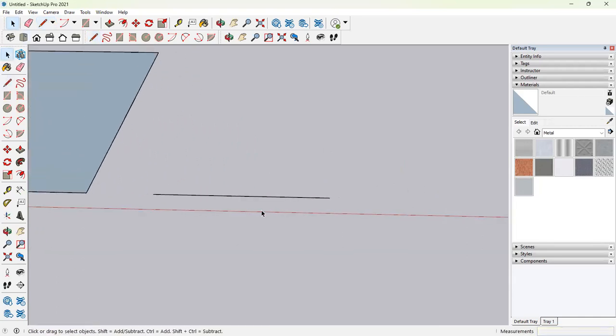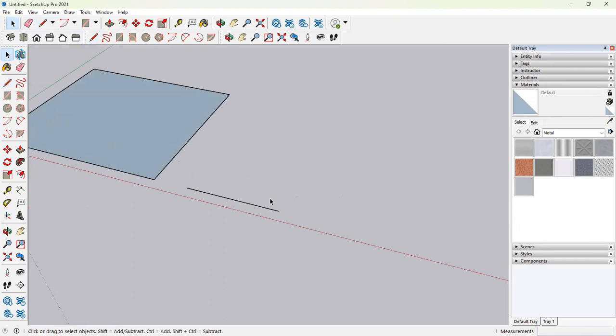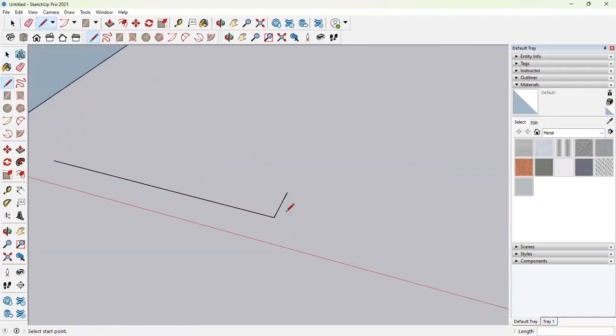This is very important. Dimensioning in SketchUp is very easy. Like in Revit and other softwares where you have to first select the units of the file, in SketchUp, there's no need. In SketchUp, you can draw in mm, meter, feet in the same file and it'll give you the same dimension. You just have to specify the unit of the measurement that you're doing. So let's say I take a line again and I want to draw a 1 feet line. I'll snap it to my green axis. I'll type in 1 feet and press enter and it'll give me a 1 feet line.